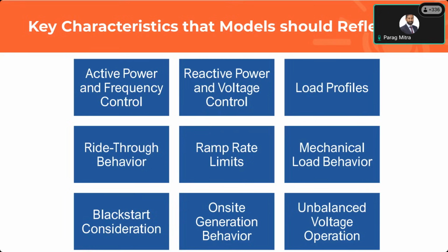Black start considerations, again, very important. If you're using this model for black starting studies, you need to make sure that you're modeling the pre-charge circuits, you're modeling any kind of controlled startup behavior, or have the ability to represent that in your model, so that if you're reusing this model for your black start study, you're able to model those nuances that these loads have during startup. If you have any kind of on-site generation, you should be able to model that on-site generation behavior.